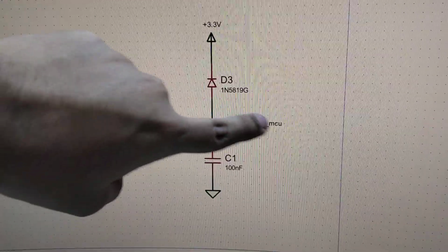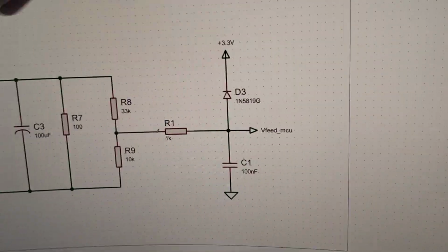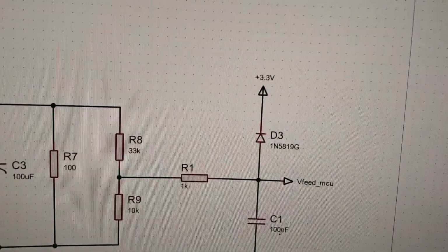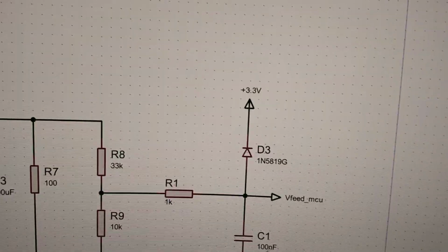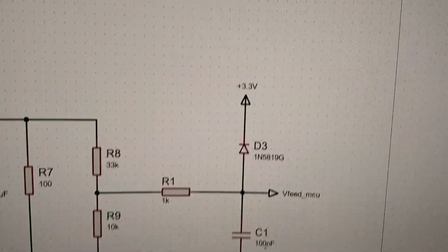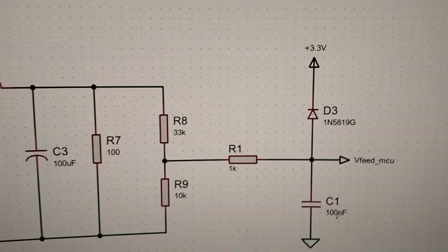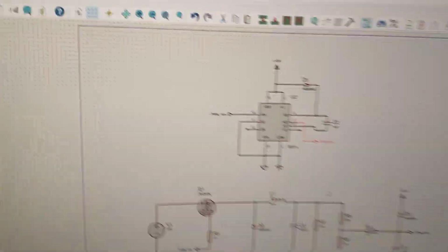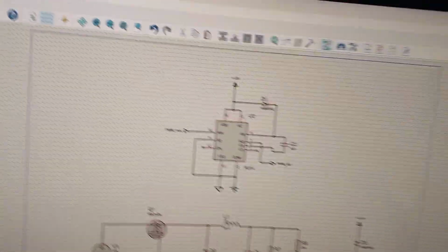So this will go to our ADC and we'll sense it from there, and it's basically a 10-bit ADC, right, the MSP430. So your voltage between 0 to 2.5 volts will basically get transformed to 0 to 1023, which is the 10-bit digital value. So yeah, that's basically the circuit. Now I'll go into the code. I won't go too into it, but yeah, this is the basic code.